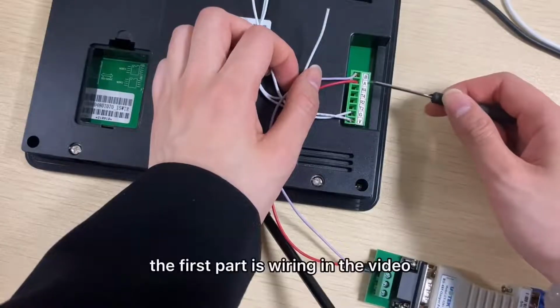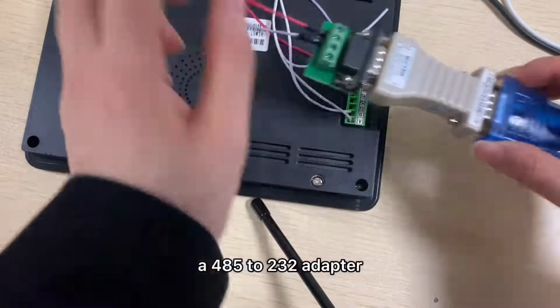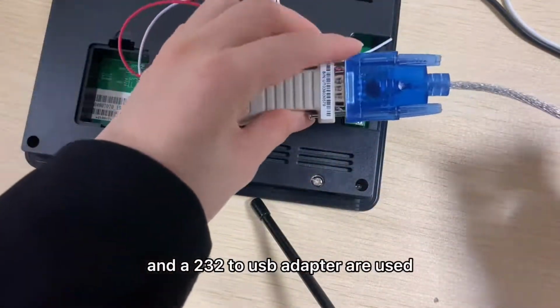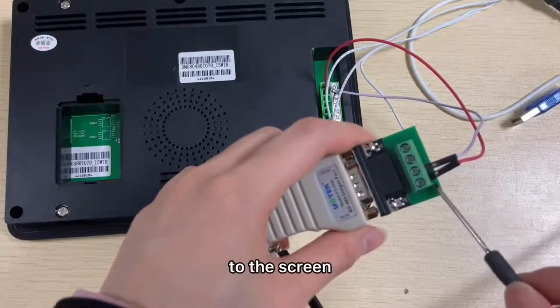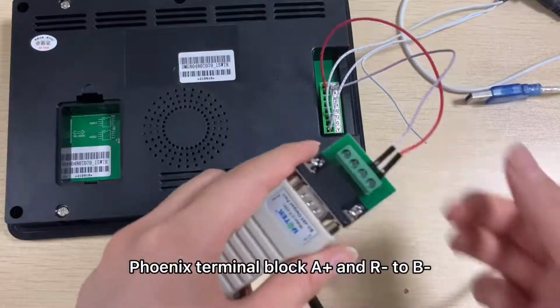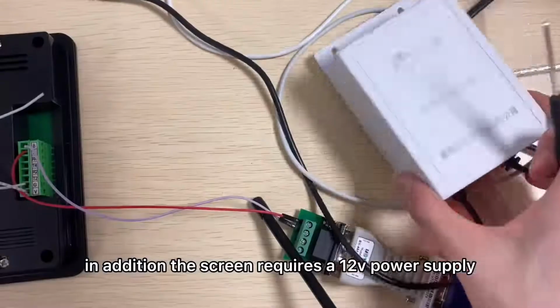The first part is wiring. In the video, a 485-232 adapter and a 232 USB adapter are used. Connect 485 R+ to the screen's terminal block A+, and R- to B-. In addition, the screen requires a 12-volt power supply.